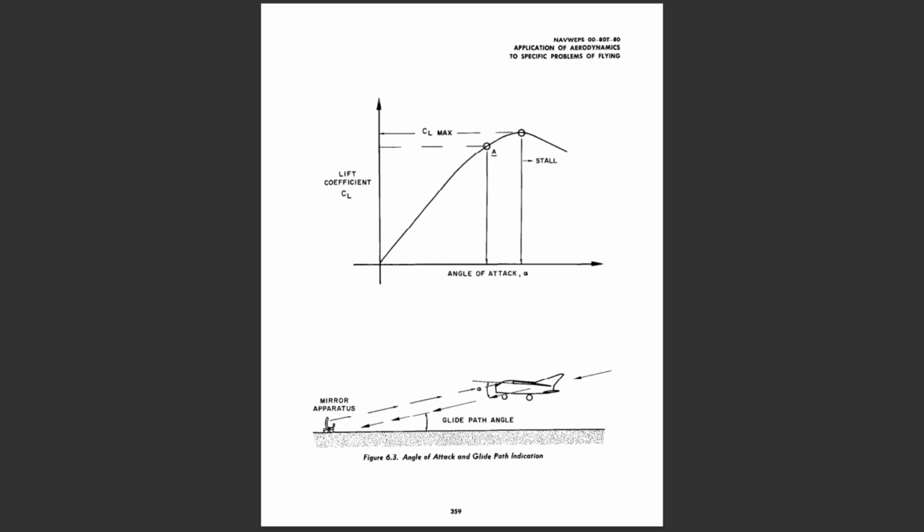In addition to the use of the angle of attack indicator during approach and landing, the instrument may be used as a principal reference during takeoff. The use of the angle of attack indicator to assume the proper takeoff angle of attack will prevent both overrotation and excess takeoff speed. Also, the angle of attack indicator may be applicable to assist in control of the airplane for conditions of range, endurance, maneuvers, etc.